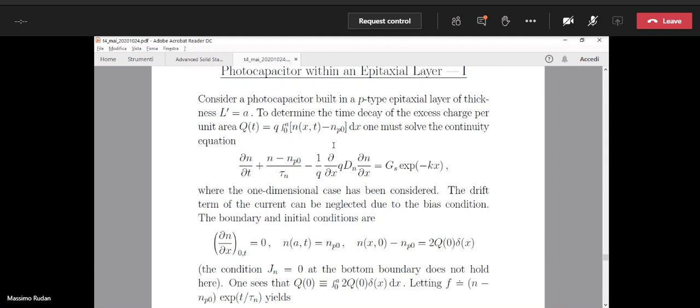However, we can consider that the expression of the current density for the electrons is essentially diffusive, because you remember, when we bring back the bias to the flat band voltage, we eliminate the field, the vertical field in the device, and the electrons move only by diffusion.